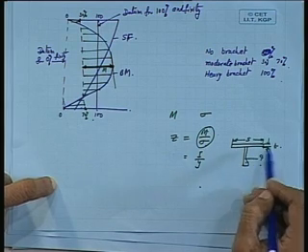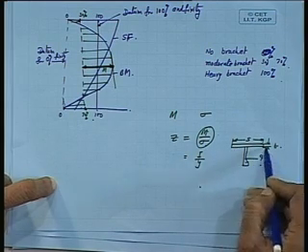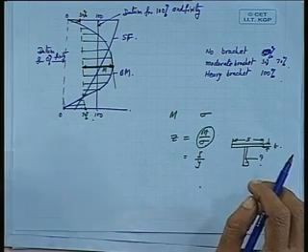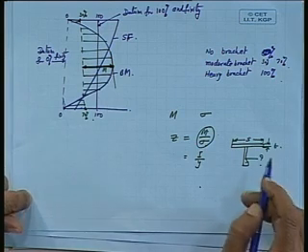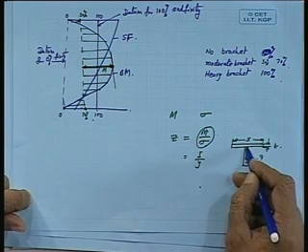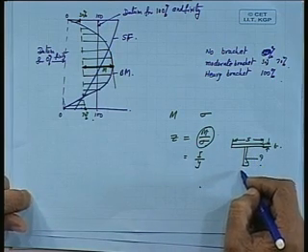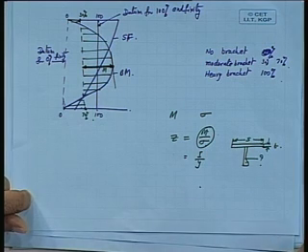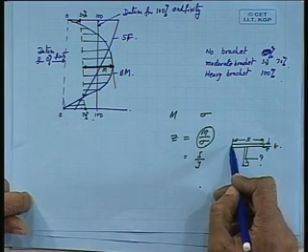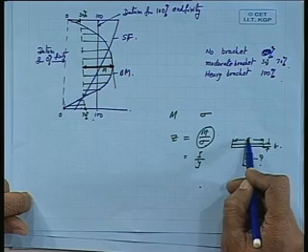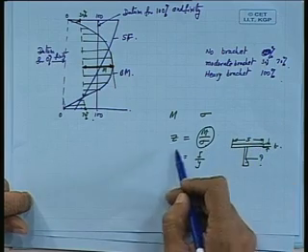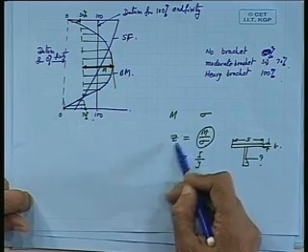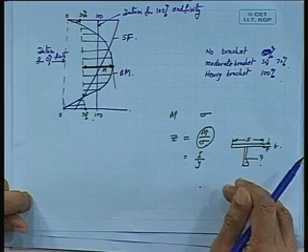Now, if the plate thickness is given to you, even then it will be difficult. You require the stiffener particulars to know about its section properties, and then you can add this plate thickness here to come to what the section modulus should be.